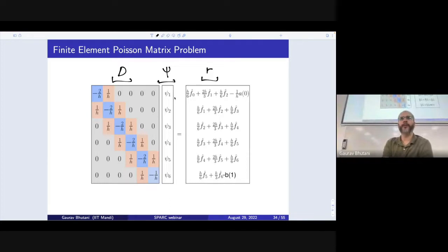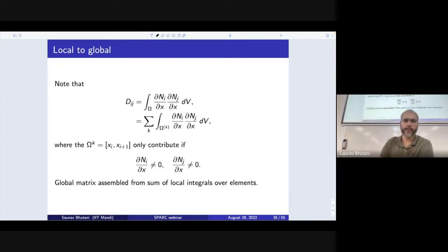And as we saw, if we change the weights of the basis functions, we can change the function. Now remember, we chose linear functions, right? And we have del n by del x for different n values. If you look at one particular element, out of the many n's, only two of these contribute to a given element. One is the contribution from the one going up, and the other is the contribution from the one going down.